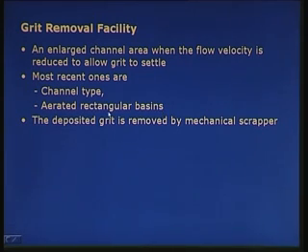We have rectangular basins specially designed as grit chambers, and again the same principle applies: I decrease the velocity of flow, and when the velocity of flow is decreased, particles will settle down in the grit chamber, and they are also aerated.